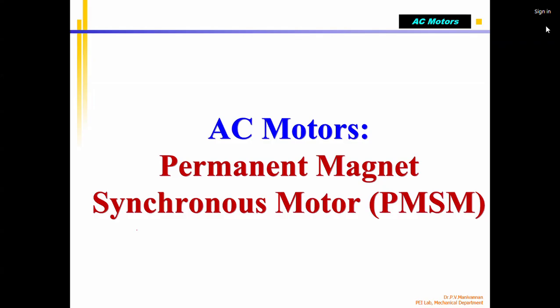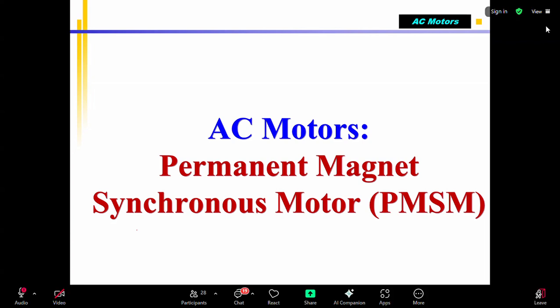Synchronous motor, yesterday I told you that it has a 3-phase winding which is supplied with 3-phase AC voltage, which generates a rotating synchronous magnetic field. The rotor is a DC magnet. It will be supplied with DC voltage. Because of that, the rotor's north and south poles will get locked with the rotating magnetic field. We already saw the vector, how the resultant magnetic field starts rotating.